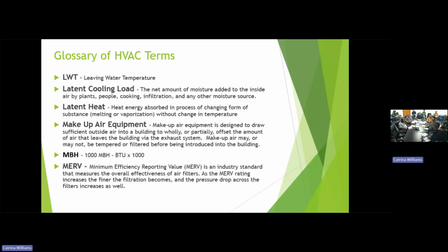Well, we like to have a makeup air unit that tempers the air and hopefully filters it too. So we're bringing in clean, I use the term neutral air into the space. That neutral air can be either a cooling or heating application, depending on what they're trying to do and how important it might be for their operation.